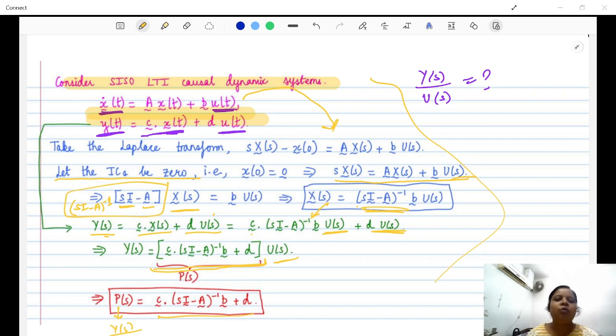You have been able to find some sort of relation, which you can say is the closed loop transfer function of my system. So this is the way in which your state space representation is really related to what you have already seen as a transfer function. In transfer function, you took the initial conditions to be 0. You have done this here also, just to obtain the transfer function. So you got the transfer function in the form of some matrices. Okay.